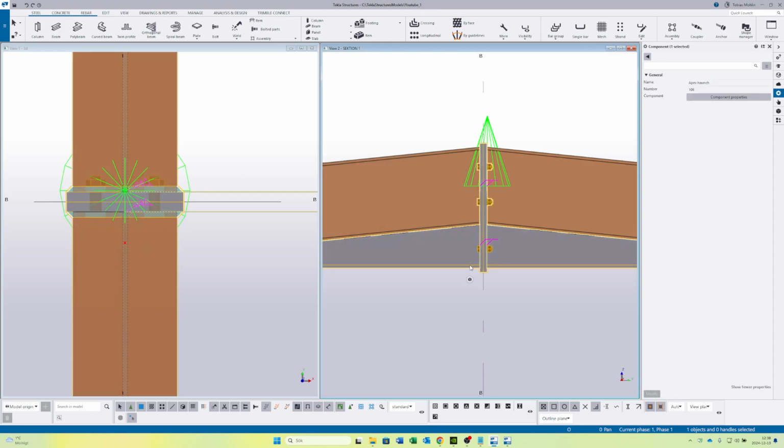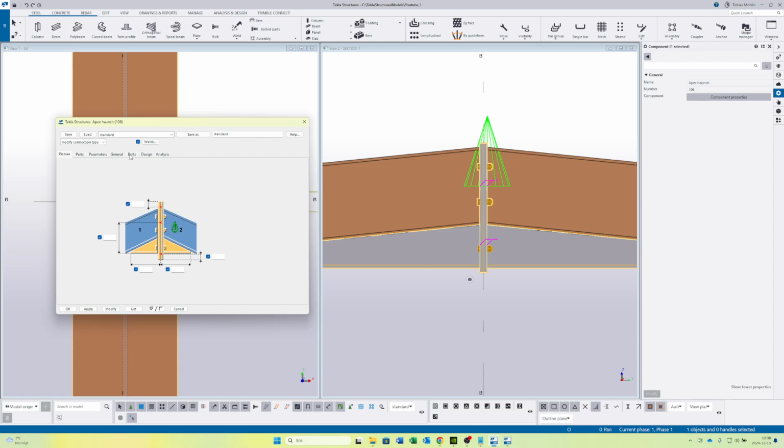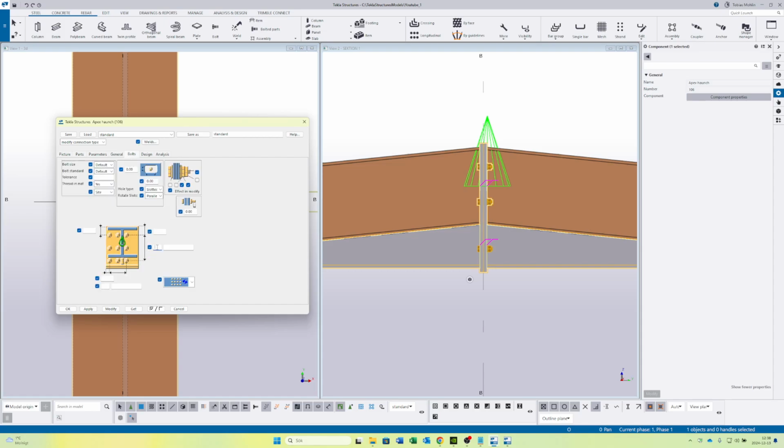Now I want to add a few bolts. I think that this is a bit too few, so let's go into bolts, and let's say I want 5 bolts maybe. Now I want the first 2 spacings to be 90 apart. But after that, I want a larger spacing of, let's say, 120 before there's another spacing that's 90. Okay, that's okay. But I want it up a bit. So let's say 50 from the top, right? Ah, that's a bit too little. Let's go with 80 then. 80 might be good. Yeah, perfect.